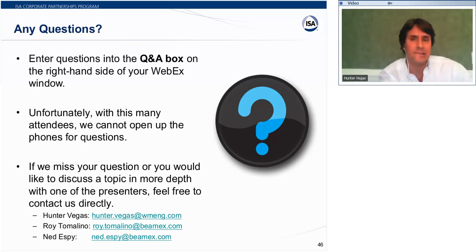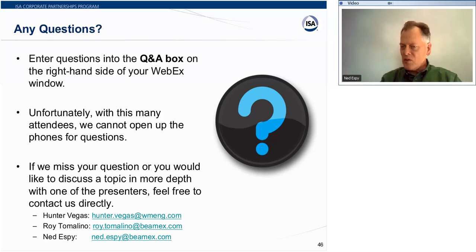No, my thought is you're going to have to remove it and then use what Roy's using in his office today, where he's got a mating flange with an NPT port, so it seals, it covers up the seal and allows you to make a connection with the hose to do the calibration. So, that's kind of the point of my slide: you need to design it up front where you can somehow get in there and make the in situ connection. That needs to be done from the very beginning, or considered at the very beginning.